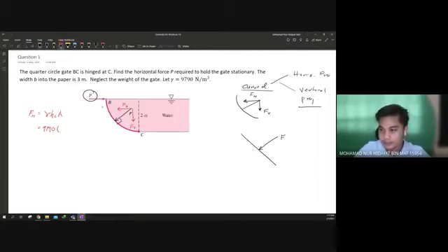Why? Okay, this is the reason. Where is your force? Your force is horizontal, right? FH in this way. So your eyes supposedly facing this way, parallel to the FH. So when your eyes is parallel to the force H, that means it is vertical projection.